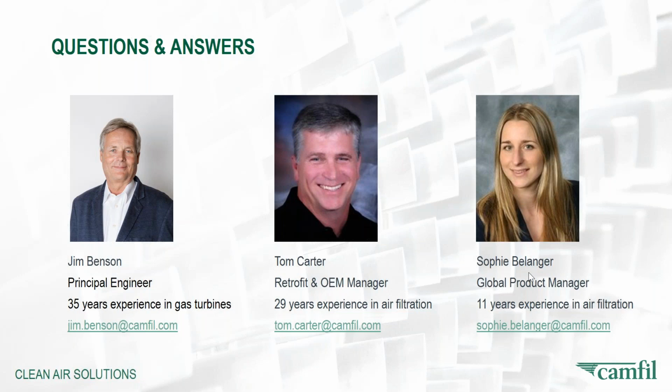Tom, and just yeah, I have a side note to that. I think that offline pulsing can be very valuable, especially in high dust concentration areas. If you can program your pulse controller to run one or two cycles with the system offline, it can be very effective to avoid re-entrainment of dust. Good point. Yeah, I think that makes about the time we had here for Q&As.